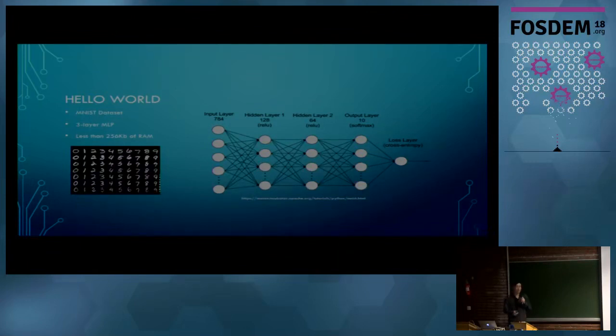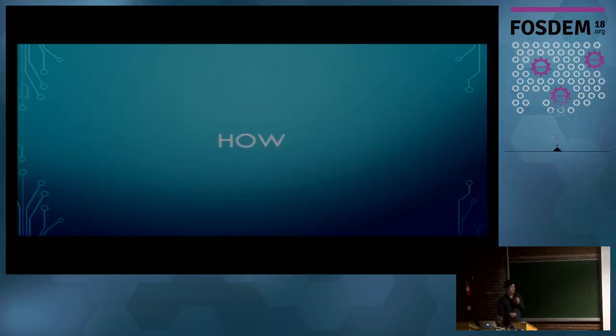And the lowest memory footprint we can put this on the microcontroller is about 256K. But if you do the math, it's actually taking less than 100K. It's just other things that we need to get a touch screen and whatever operating system running that also take the RAM. But there's a lot of room to be optimized here.